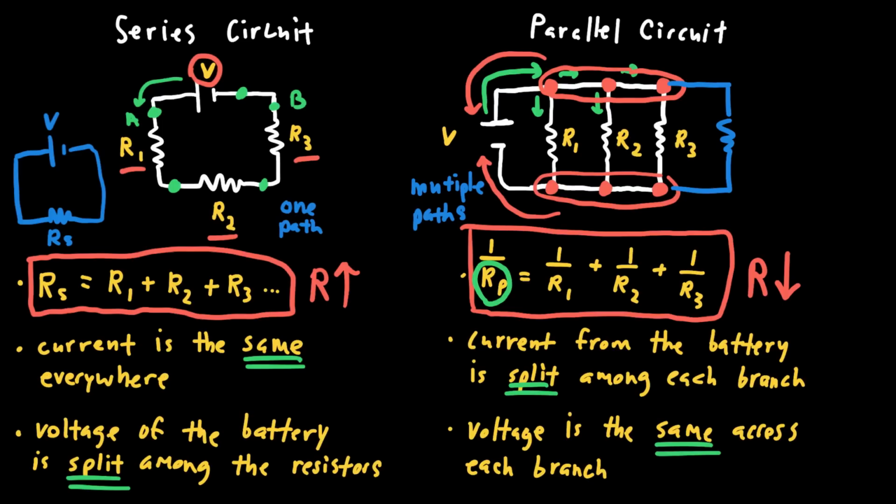So in general, the equivalent resistance of a parallel arrangement will always decrease. And if I add another resistor, that's another resistor pulling more voltage from the battery that's equally bright. The battery is going to die even sooner, but the equivalent resistance goes down because in order to provide that same voltage difference across each resistor, even when the new one is added, there has to be more current that's pulled out of the battery. And that is corresponding to a decrease in the resistance.